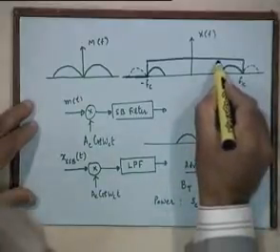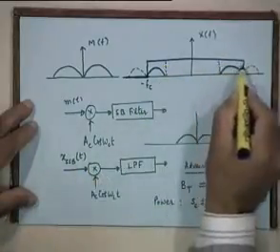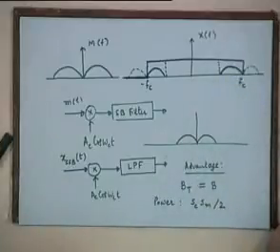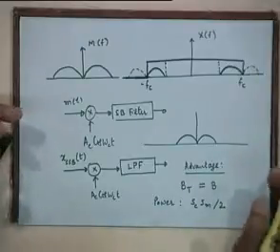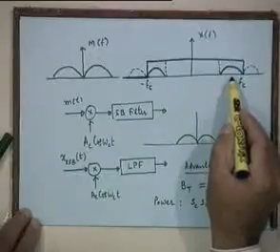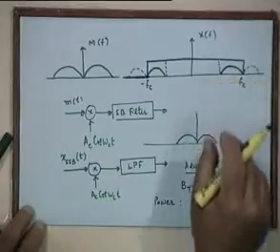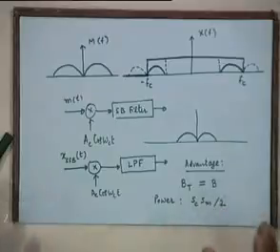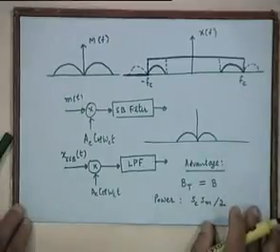In practice, of course, you will not realize a low pass filter, you realize a band pass filter, which will have this transfer function, but it will also be associated with the same difficulties, right? One can approximate such filters. Basically, you require what are called high Q tuned filters, because typically these carrier frequencies are very high, and this bandwidth will be a very, very small fraction of the carrier frequency. So a narrow band high Q tuned filter will do the job, right?